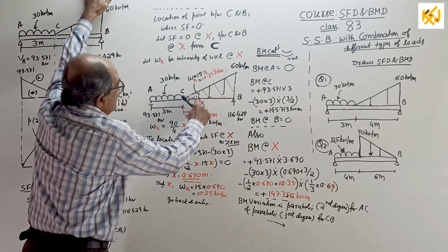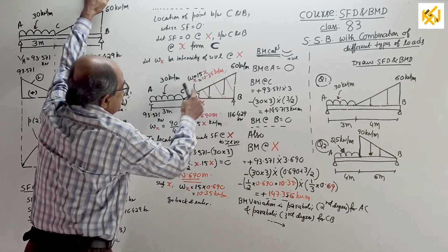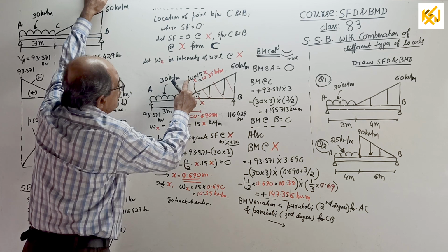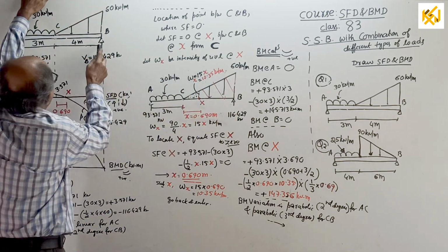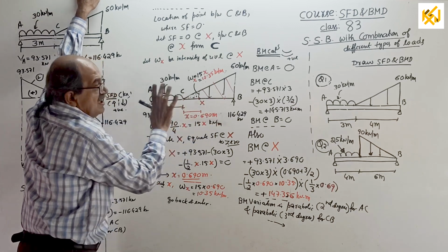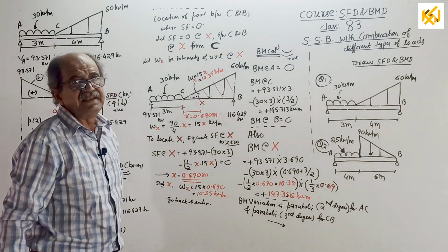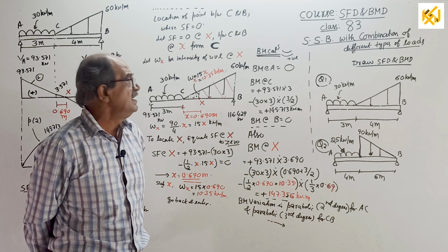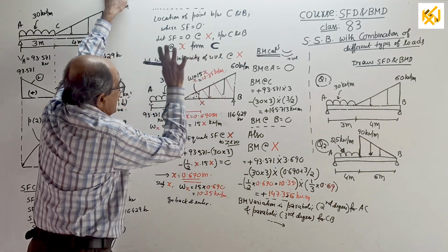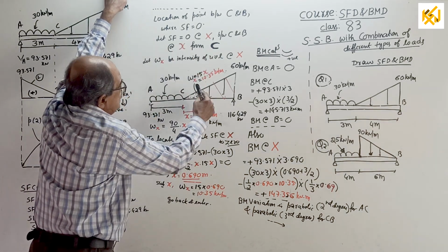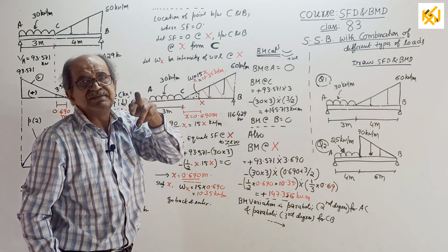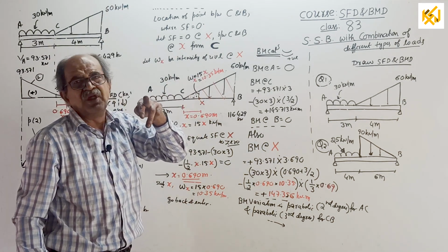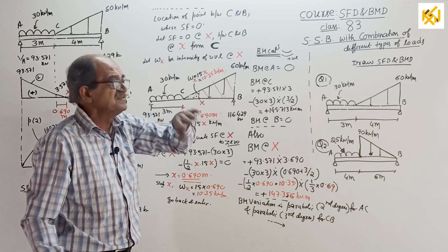See, somewhere here X. It is 60 here, 0 here, intensity is W suffix X. Get it? 60 by 4 is here, into X will give 15X kN per meter as the intensity. Now, at present 15X, enter there. Now, shear force is 0 here. Remember, I told this in a mathematical class, I don't know the number now, go through all those 3 classes.